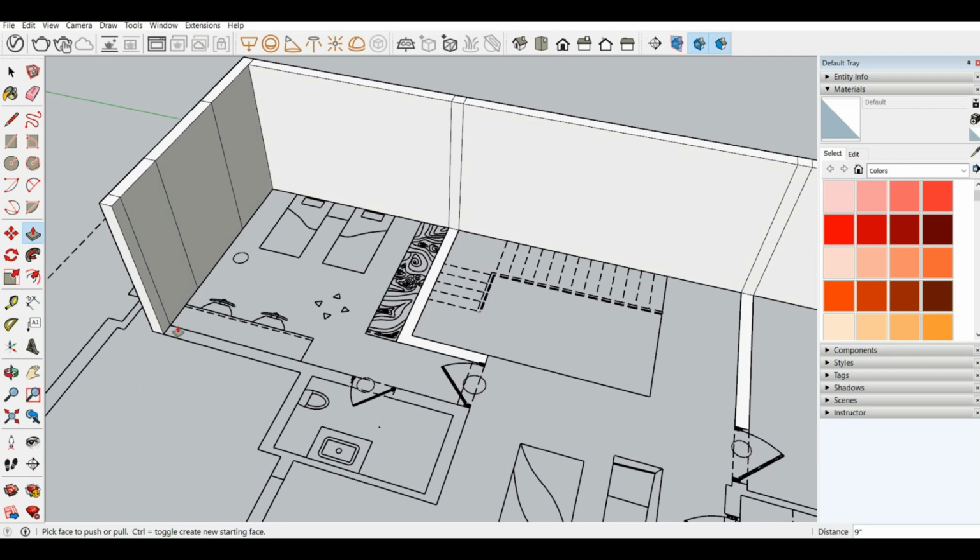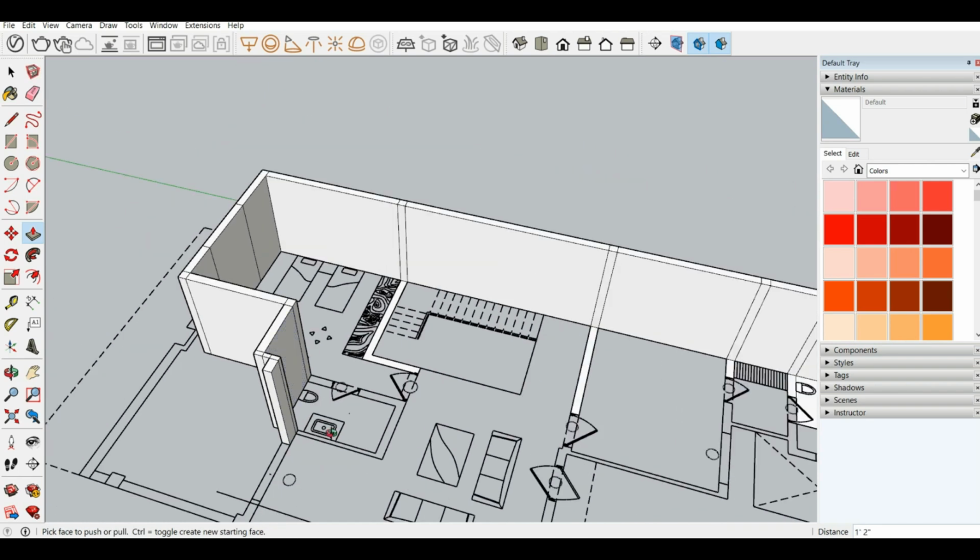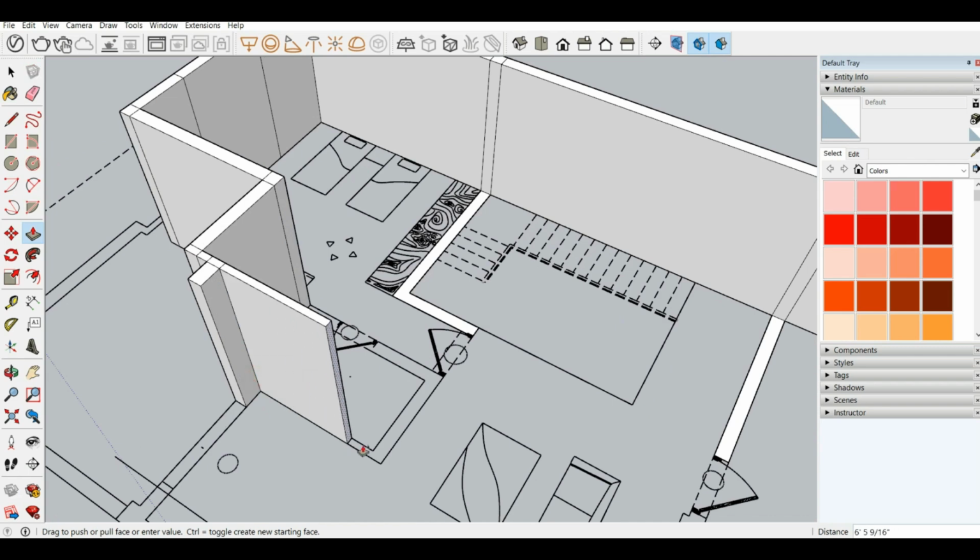So it's the same thing over and over. Now just one thing to remember is that when you meet two walls of different width in continuity, for example here, we will give 4.5 inch. In this area, a 4.5 inch wall is required. So then we'll stretch again. Now again it's 9 inch here. So like this you can shift from one dimension to another.